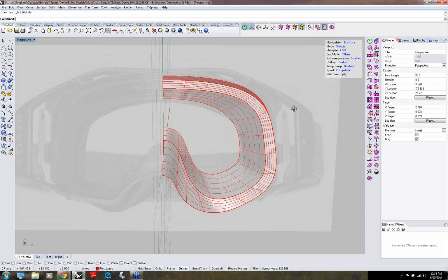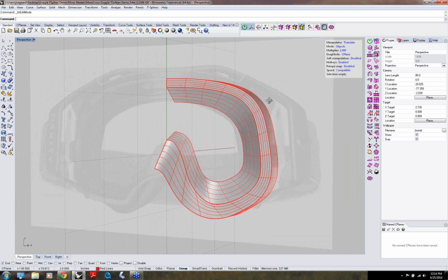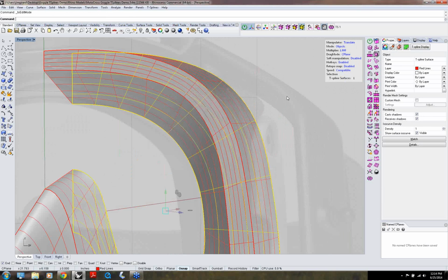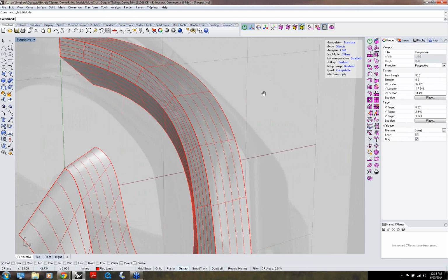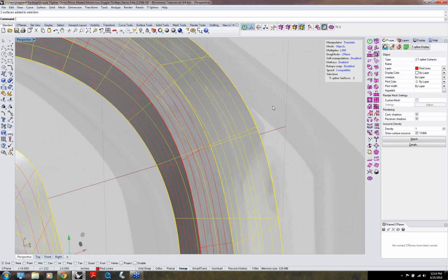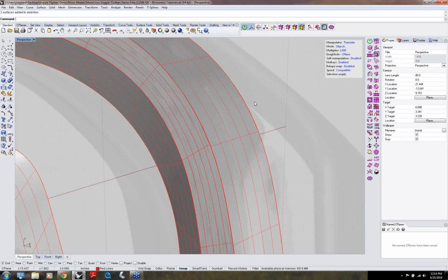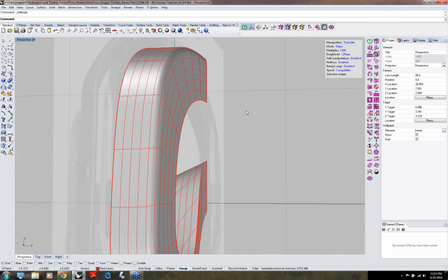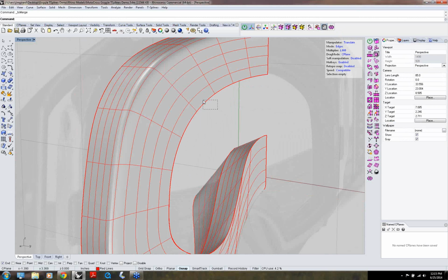And now when I'm in T-splines, and I select a surface, you'll see it's a T-spline 1 surface. Now here's where this makes sense. If I go right to left and I grab the two T-spline edges here in the heads-up display, if I grab the two edges, and now I say loop, and then in my T-spline I say weld edges. Now I've got a nice tight edge that I've welded. Again, loop, weld.